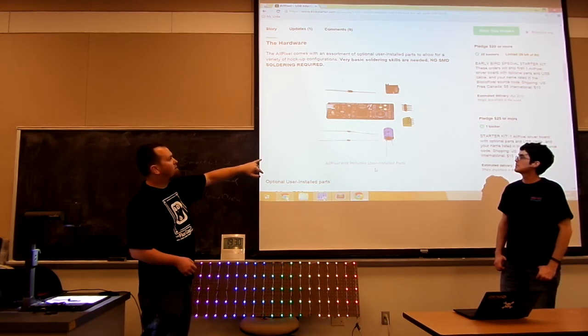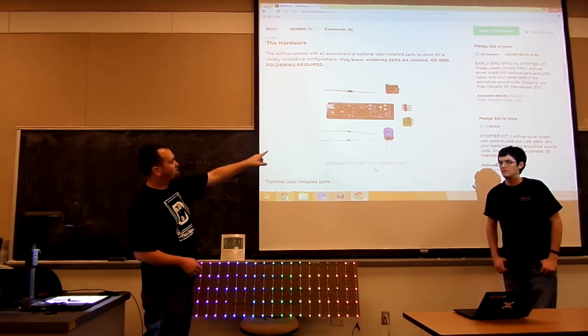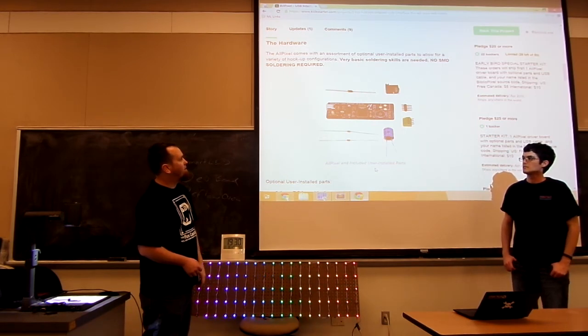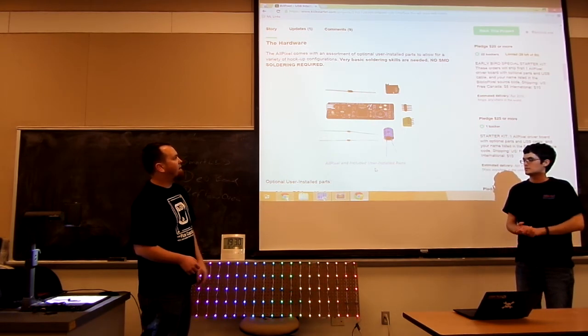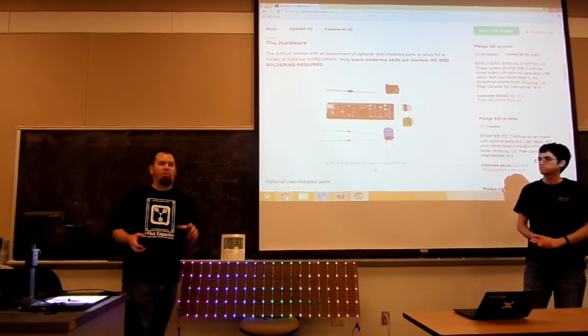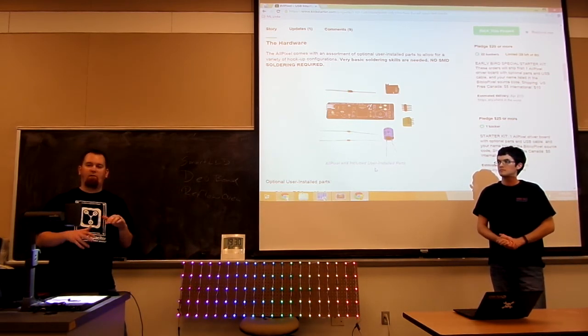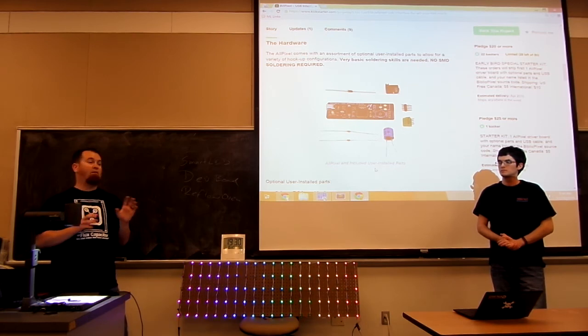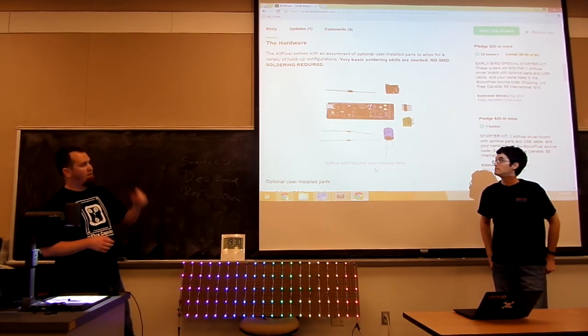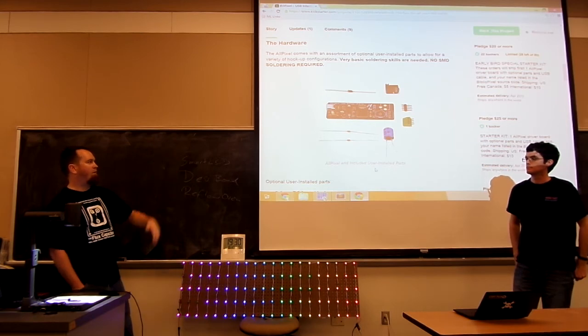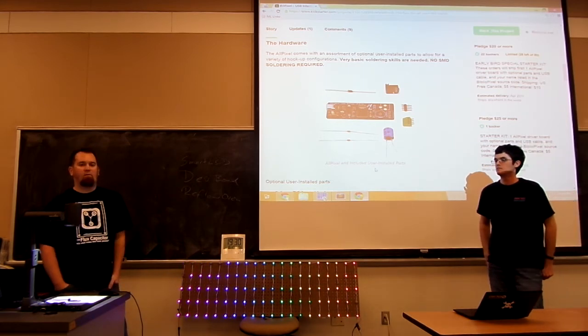We've got a couple of optional resistors, which have jumper pads, right to the left of the C5 capacitor there. Things like NeoPixels often are a little bit better if they've got a resistor in there just to lower the logic level voltage. It protects them a little better. I've fried far too many without it. And then the screw terminal again, as well as a standard 4-pin header for connecting to a breadboard.